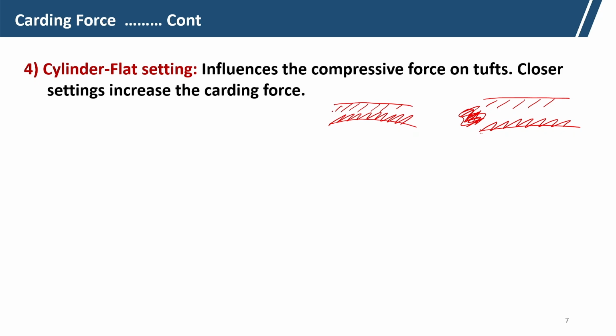With the setting closer and the same material, a closer setting will result in higher compressive force on the tuft, and a closer setting increases the carding force. So, if we reduce the setting, the carding force will increase.